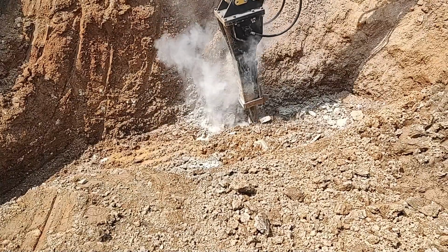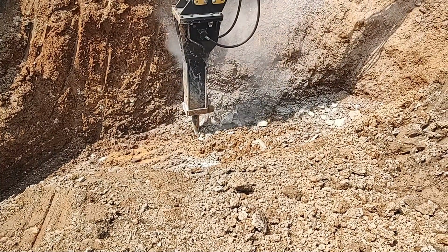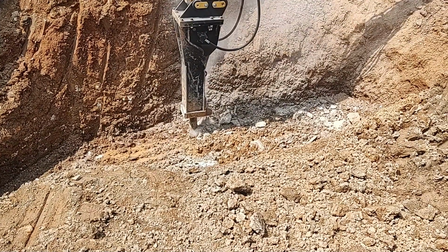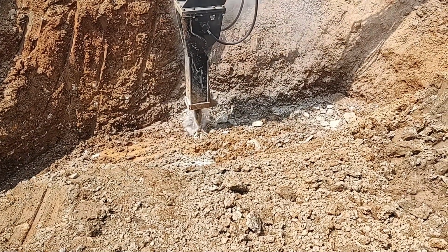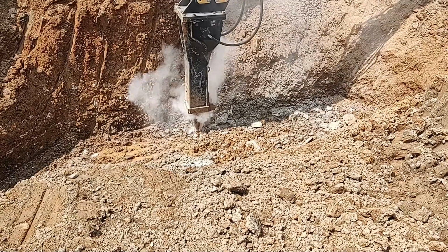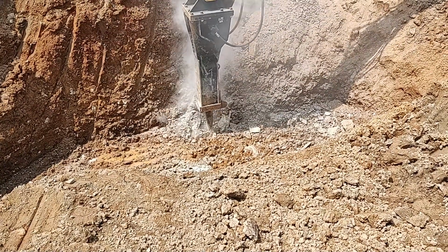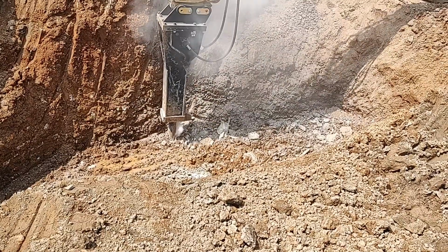We rented a breaker attachment for the excavator, and this was done at great expense so we could break up layers of the limestone rock near the surface. The breaker attachment works like a giant jackhammer to crack large pieces of rock. One must take their time using this tool and not use it as a pry bar or it will break.